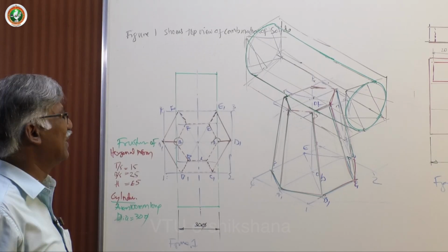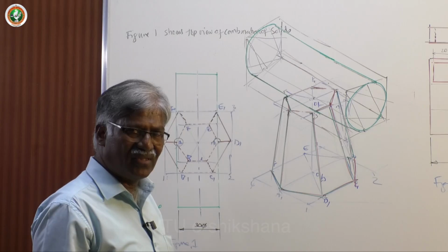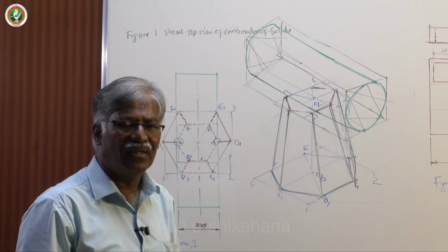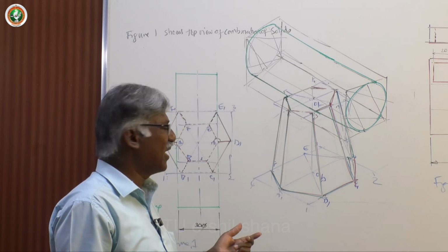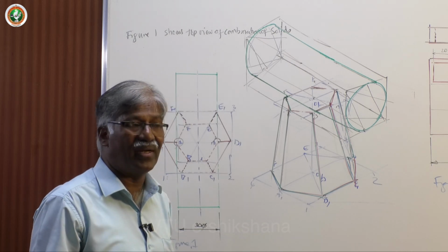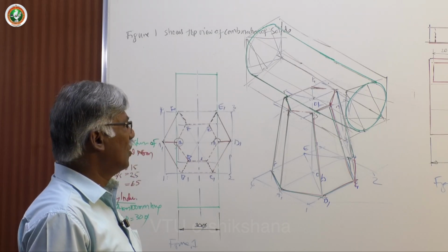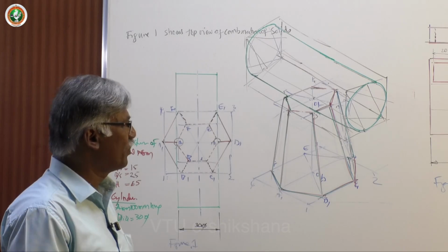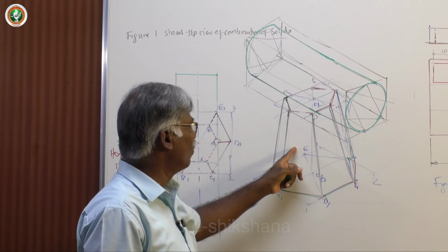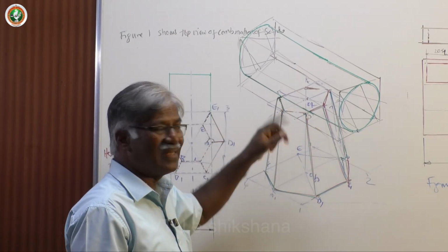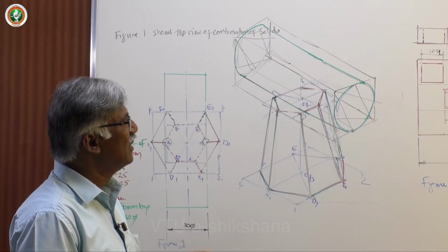Now this is how you complete the isometric view or projection. Projection means taking the reduced length; the view is taken directly. Suppose in the computer you do it completely with the actual length, reduce it by 0.816. That gets you this. So it is very interesting to work these problems. It is challenging to place this manually, but on the computer it is easy. I will show you. But manually it's challenging.